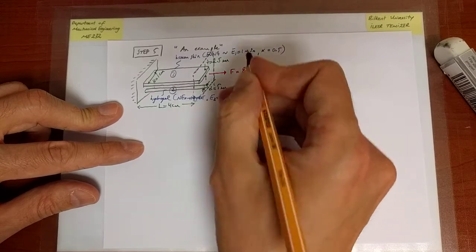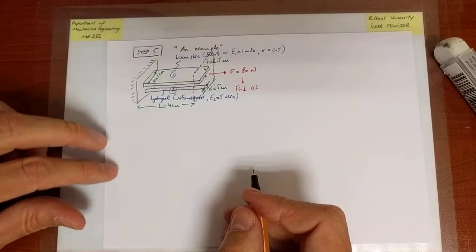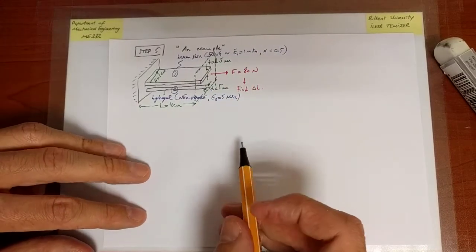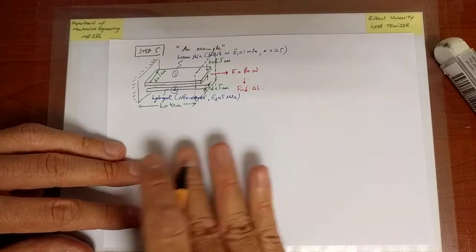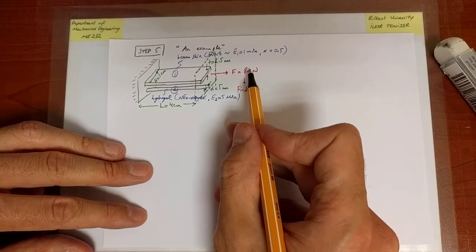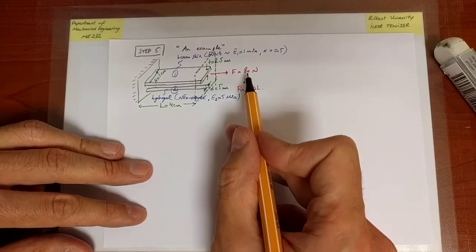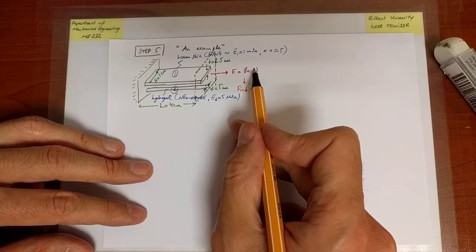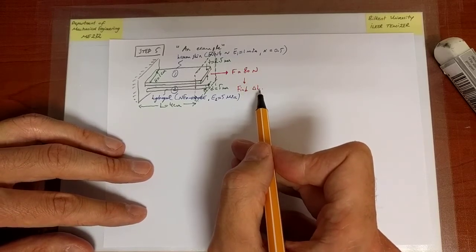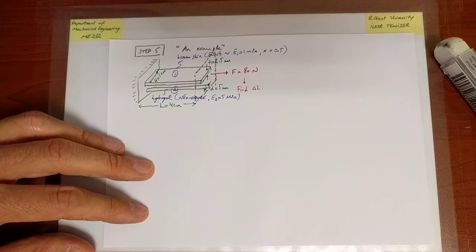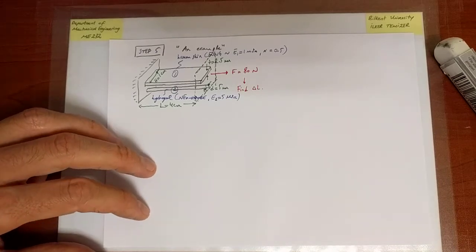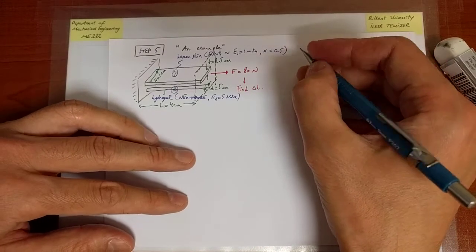Notice that the moduli are extremely small because we're dealing here with highly deformable materials. Okay, so that's what I'd like to do. I have the force and I'd like to find the displacement. So eventually I'll know what the stress is in some sense, and I'm trying to find this stretch, and therefore we need some nonlinear equation solution capability, right? And that's why I introduced the bisection method in the earlier slide.